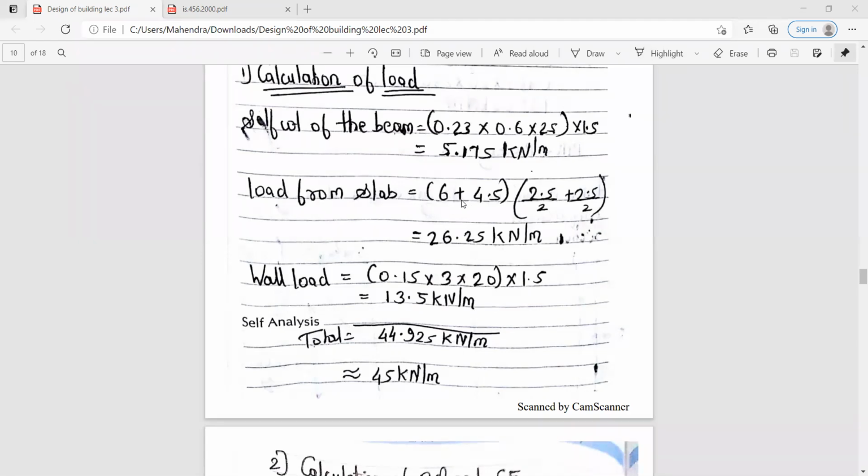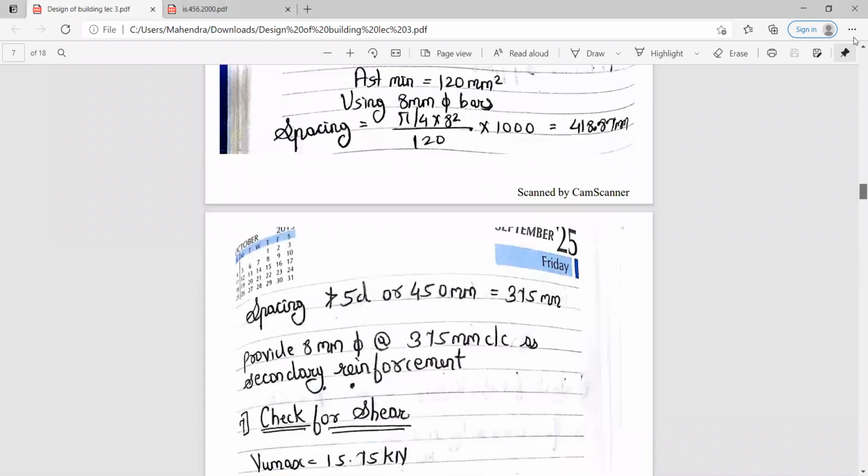स्लैब के लिए देखो आपको सबसे पहले क्या लेना है, डेड लोड लेना है. तो टोटल डेड लोड आपको कितना मिला था, 6 मिला था. फैक्टर डेड लोड आपको मिला था 6. देन फैक्टर लाइव लोड यू हैड गॉट इट एज 4.5. देन go to the diagram, see your diagram for beam B3. B3 के लिए डायग्राम देखो, B3 का स्पैन कितना है, 2.5 का स्पैन है.